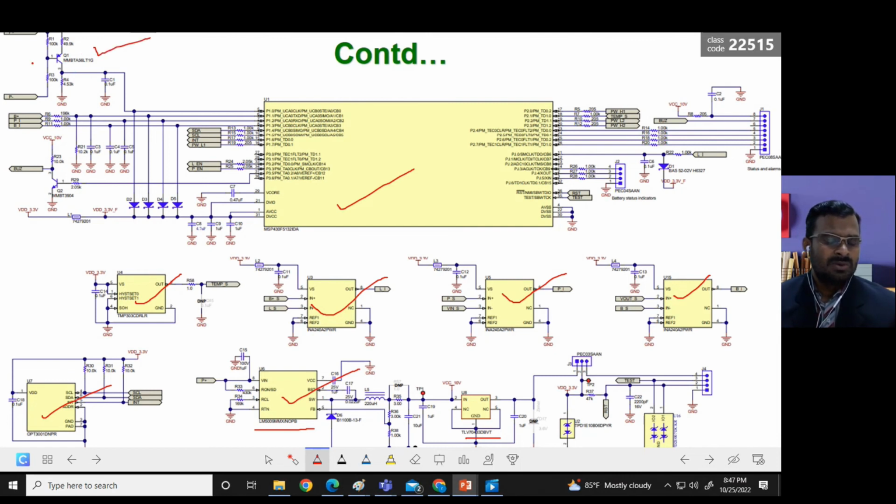So these are the inputs, the voltage sensor, temperature sensors, and all these are inputs for the microcontroller. Based on the conditions, it gives a signal for the switches to turn on and off, so that the connection and disconnection of the battery and panel is controlled. Also, the charging rate will be controlled. By controlling the charging rate, we are able to obtain the maximum power point for the given ambient condition and load condition.